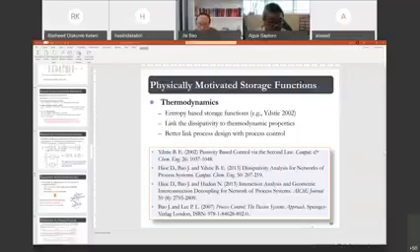And one of the problems of adaptive control is how you ensure stability. So I'm not sure whether the question you just asked is related to improving the model over time and using the model for MPC. Obviously, what you have to do is recursively improve the model that is used in MPC. But the question here is how do you ensure stability?